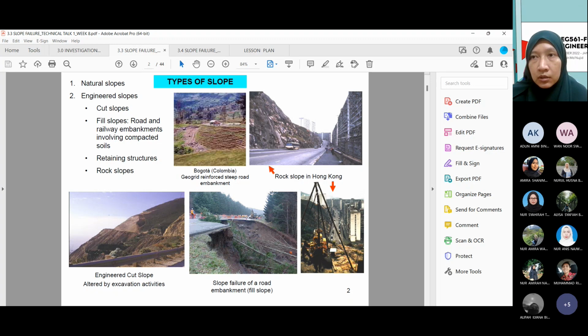Because when we have a case failure, the public authority will hire certain private engineers or a group of engineers to come to the site, investigate the causes, the effect, and what the best solution is that can be taken by public authorities, so that in future we can minimize the failure or any losses. The important part of the technical knowledge is to understand the theory behind the failure itself. I mean that you can identify the slope failure category, and in terms of strength, stability, failure mechanism, what calculations are involved, what theory is behind it, how do you calculate the factor of safety.